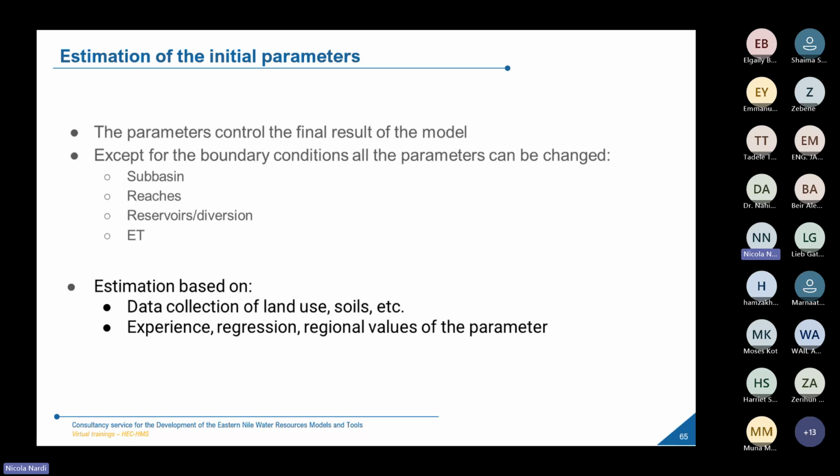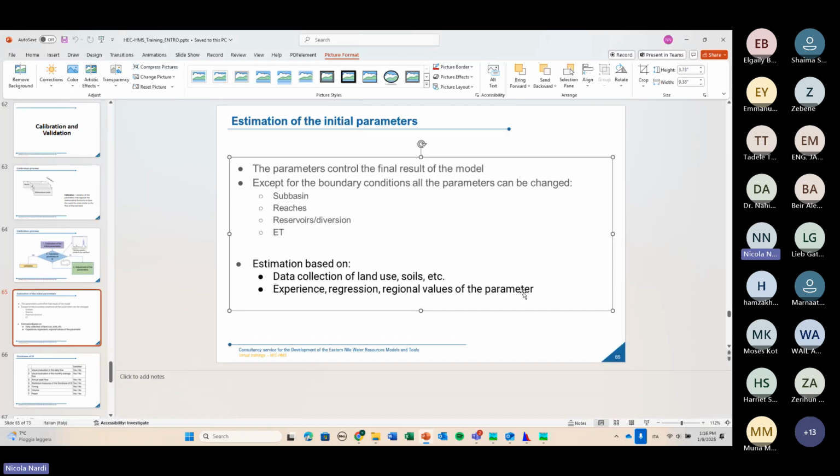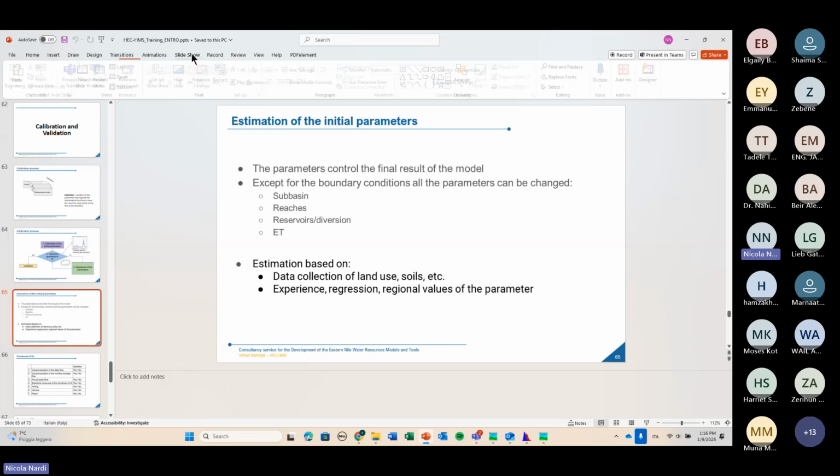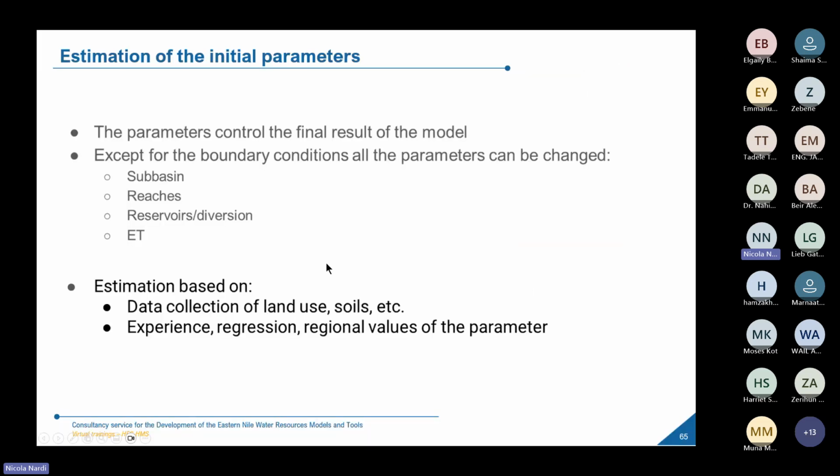But in general, if you are talking about, for example, the infiltration, the land use, the impermeability of the soil, there are multiple ways in which you can do it. The first one that I want to tell you is the remote sensing, that probably here is not written. But in general, the first step that you do is the estimation from a remote sensing analysis. So you look at satellite data that can be globally available, for example, about the infiltration, the type of soil, the land use.